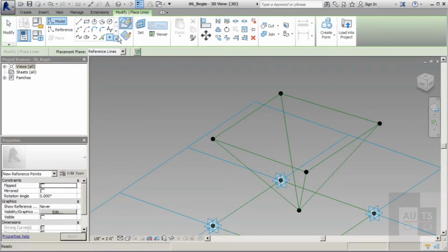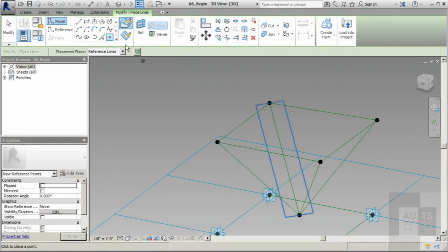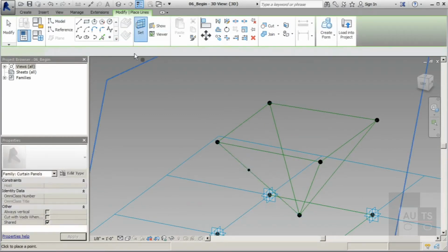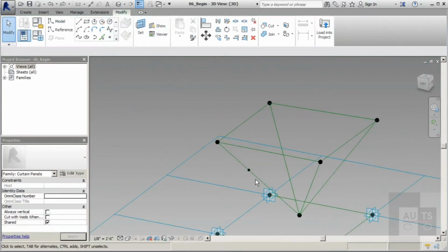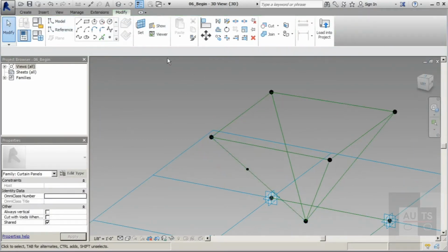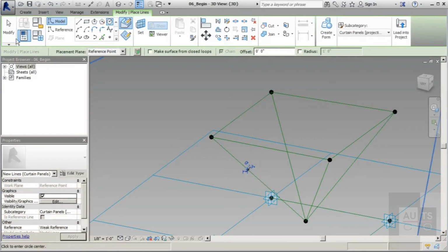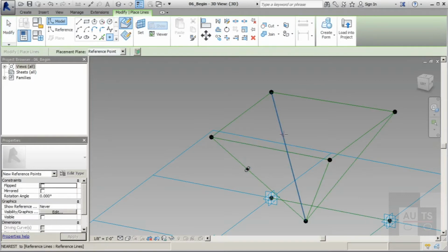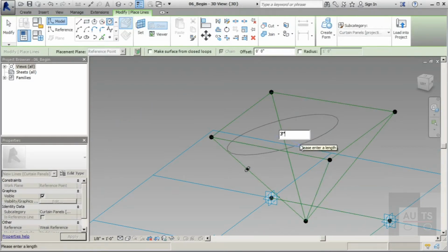So again, we'll do what we did before. I'm sure we have a good understanding of how this works now. We've done it quite a bit, so we'll go ahead and place the point. We'll set. We'll create our circle, making sure we snap on that center point up. Looks like we need to make sure we get a model reference line. Actually, we need to set that line, so we'll go Set, Select, draw my circle, 3 inches, hit Enter. We'll do the same thing here. We'll set a point, we'll set a plane, we'll draw a form, snap it in place, 3 inches for the radius.